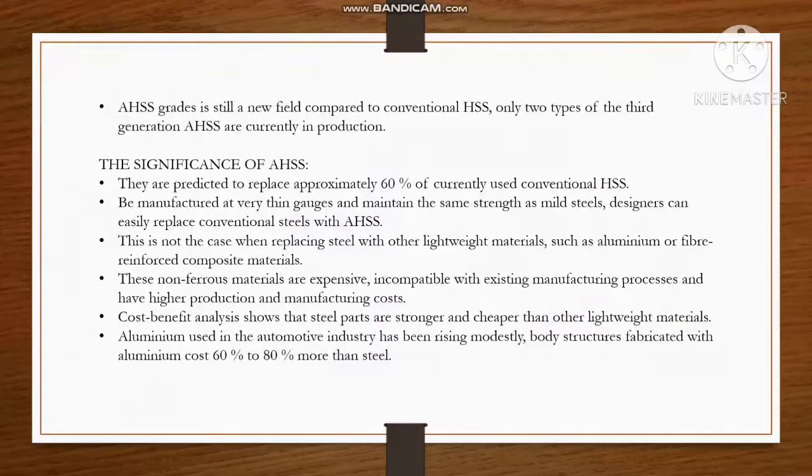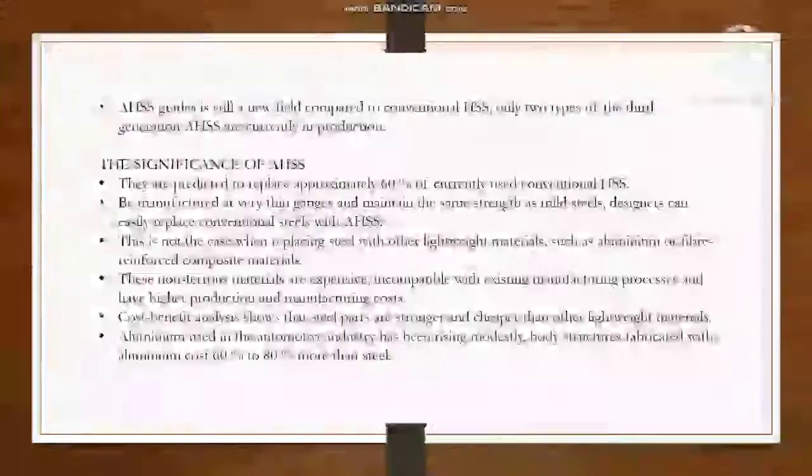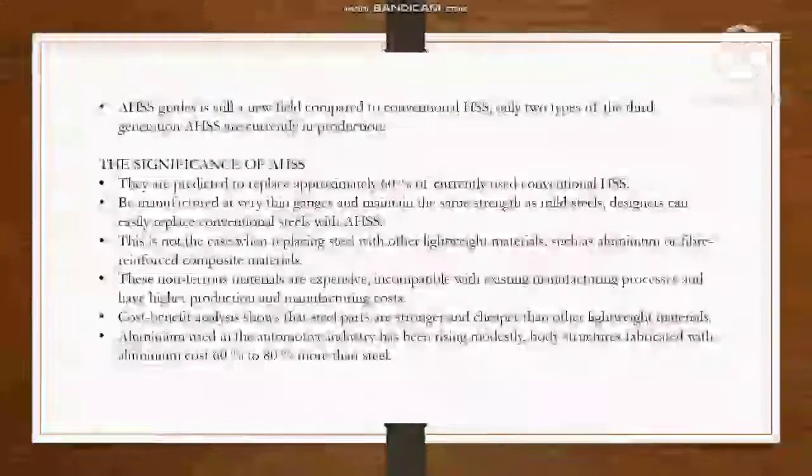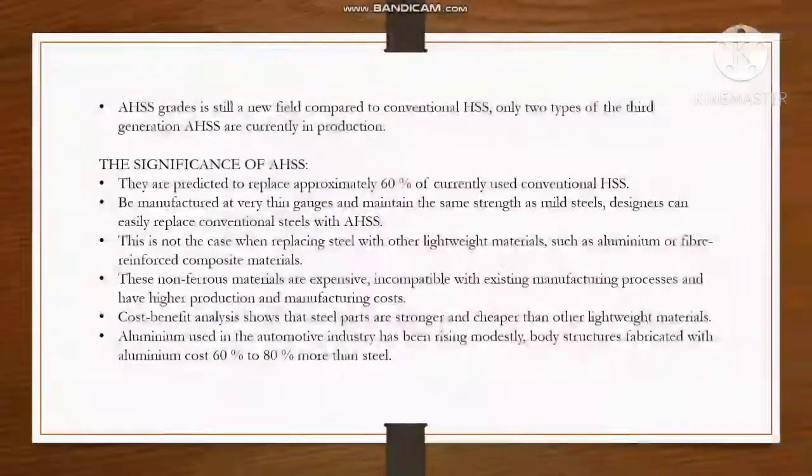Manufacturers can use varying gauge and maintain the same strength as mild steel, so designers can easily replace conventional steel with AHSS. It is not the case when replacing steel with other lightweight materials such as aluminium or fiber-reinforced composite materials.